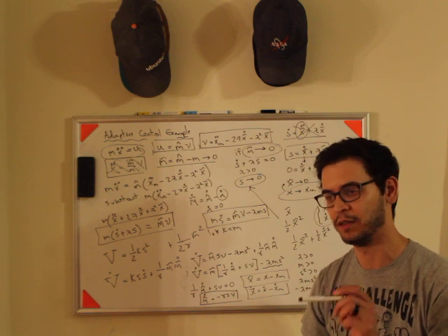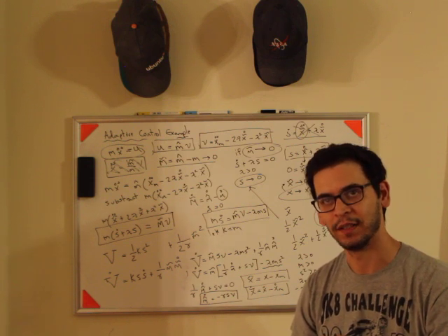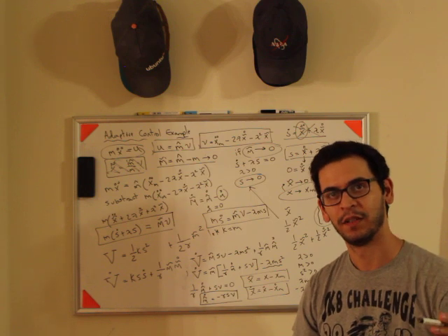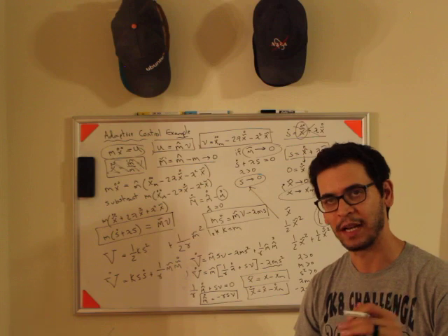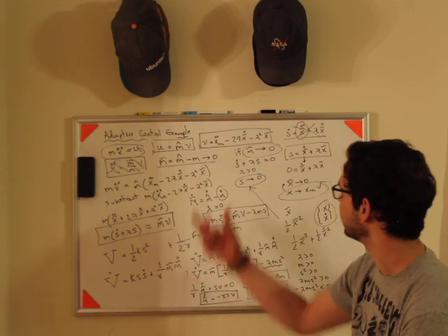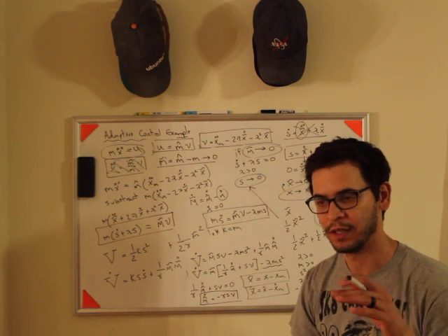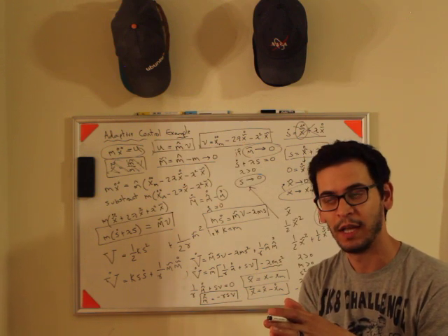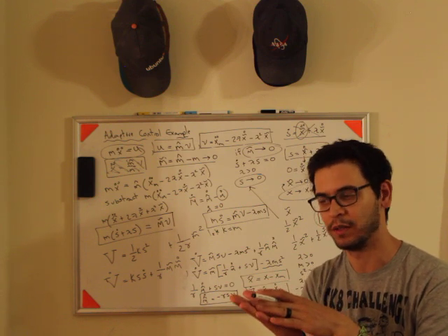And if you simulate this, you'll see that as long as your reference signal varies enough, that is, it changes largely enough, your tracking dynamics will be good after a certain transient, dictated by your tracking dynamics here. You'll see that your tracking performance will converge, and your mass estimate will also converge.